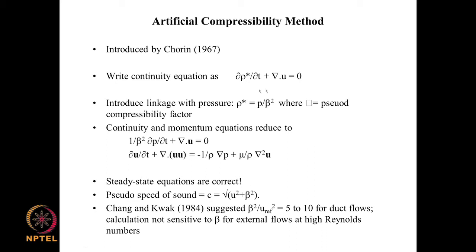and this is an equation which is not correct for incompressible flows because there is no density here, and this density is not the density that we normally have for, say, water or air. This is a fictitious density. It is brought in to create a linkage, a bridge between the continuity equation and the momentum equations. And how that bridge is built is shown here.